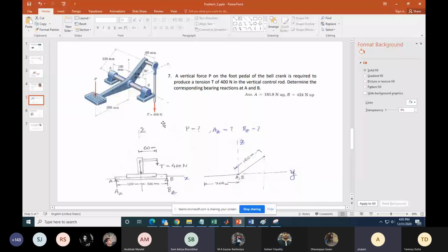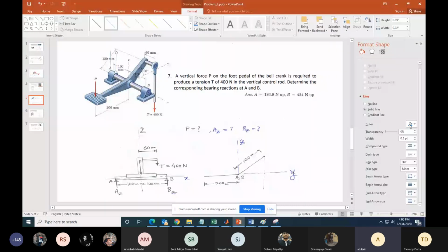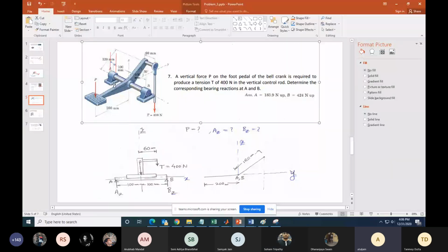And then the width of the ball bearing is not given. So are we assuming it to be negligible? I mean to say, this width is not given. This width is not given, or is it given? The bearing at B is represented by a point which is 100 millimeter away. If the bearing at B is a point, then it is allowing rotation also.